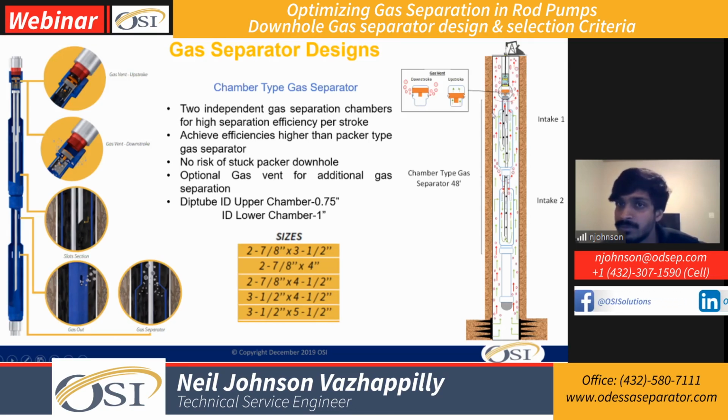So the fluid and gas separate in both of these chambers individually and purge out of the top slots. I'm not sure if you can see it entirely in this image, but we have two slots right at the top section of both of these chambers, which help purge out the free gas that enters the system. But the majority of separation happens outside because of the IDs and pressure changes. So this is pretty much the design principle of this separator.